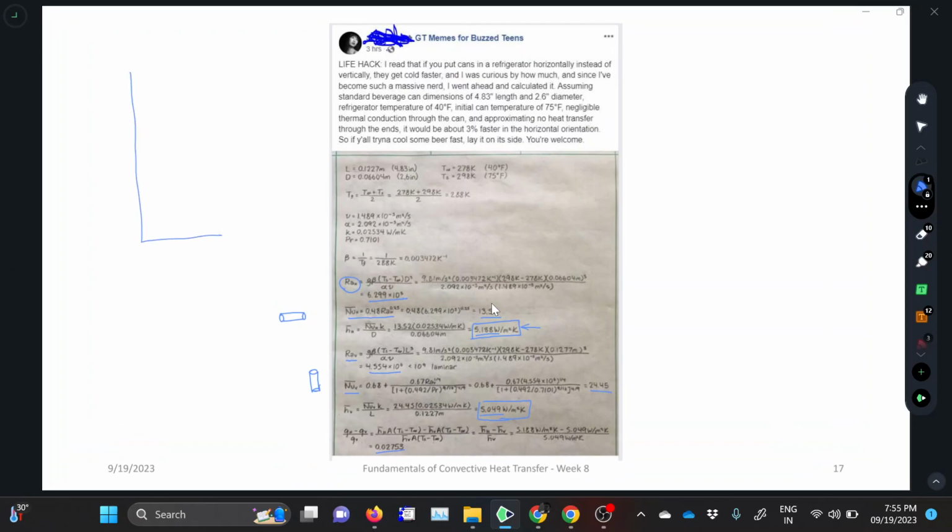Now, all this complicated math aside, if we just try to think of it from a physics perspective, imagine I have a cylinder like this. I'm looking at the front view only, and the ambient fluid is at a lower temperature. So heat transfers from the cylinder to the ambient air. A boundary layer like this would be set up, correct? Any packet of fluid over here got some heat from it, and it is only moving up, right? So there is very little temperature change that can occur if this length is much higher, because it's already heated up. It can't absorb more heat from the cylinder, right?